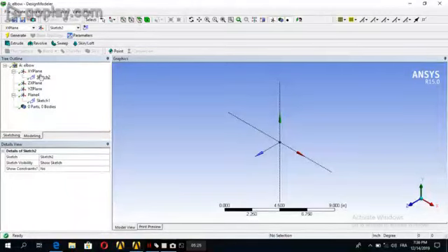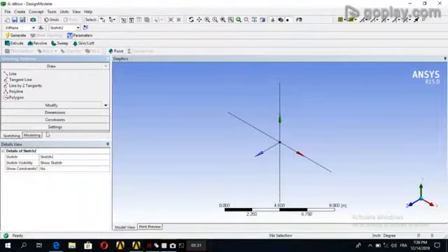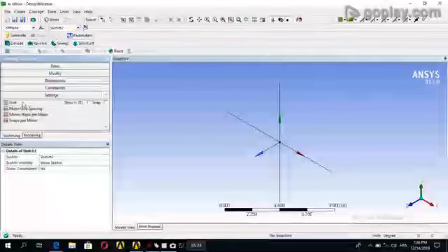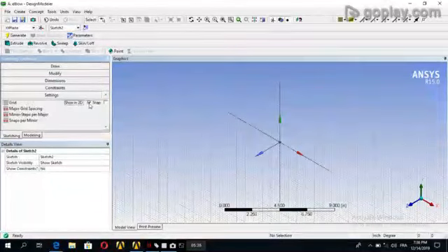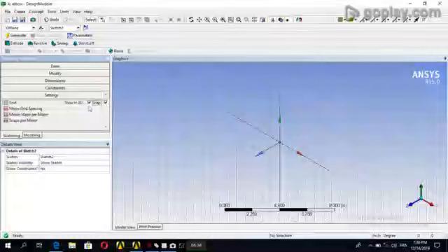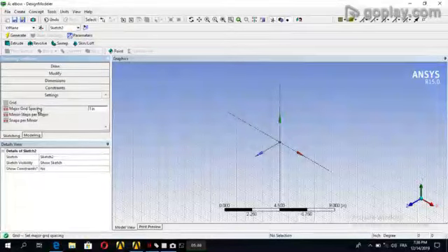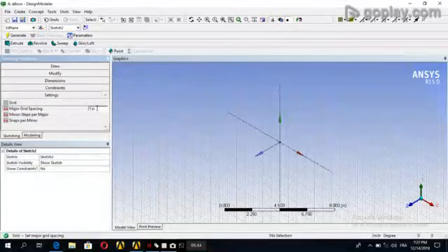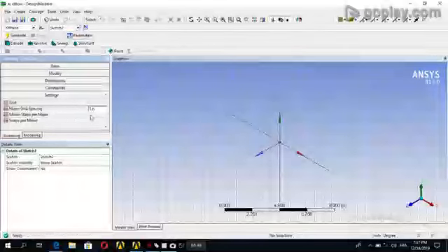And the sketch tool is based on XY plane. Now we'll go to the sketching, settings, grid, enable show in 2D, enable snap, major spacing 1, it's already 1, and minor steps per major to 2.